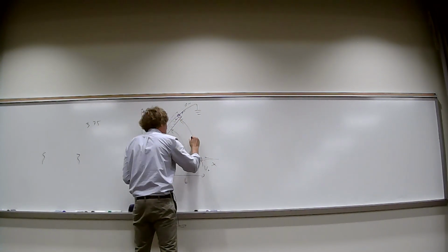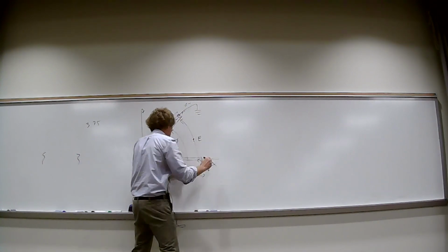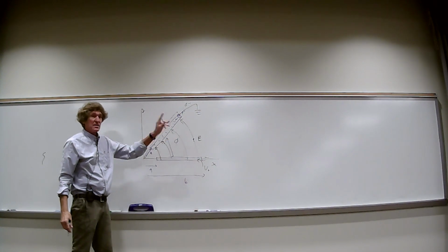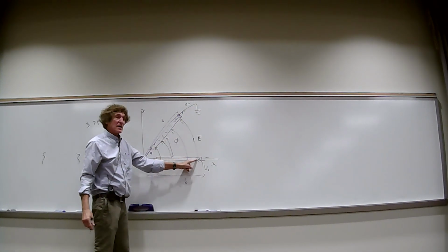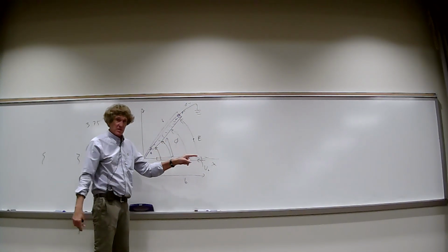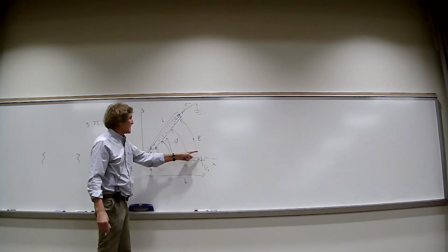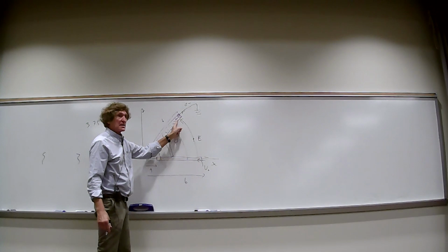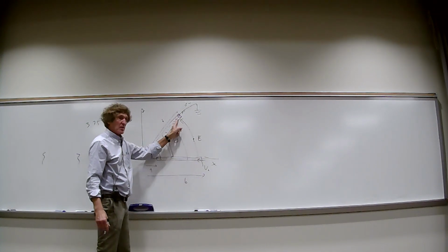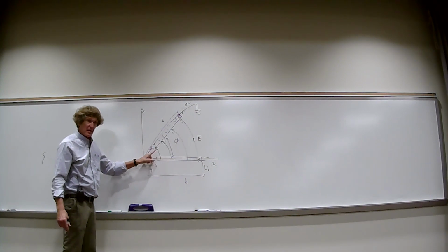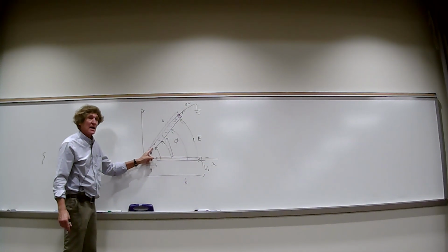And all these things, there's an electric field, but the further out you go, the less the electric field magnitude is. And here's why. When I integrate the electric field, it will be in the phi direction. I'm going to tell you this, and I'll get to this more in a second. When you integrate E dot dl from this point to this point, you have to get the same voltage as from here to here. You all see this? Well, this is a shorter path. That means the electric field here has to be higher.